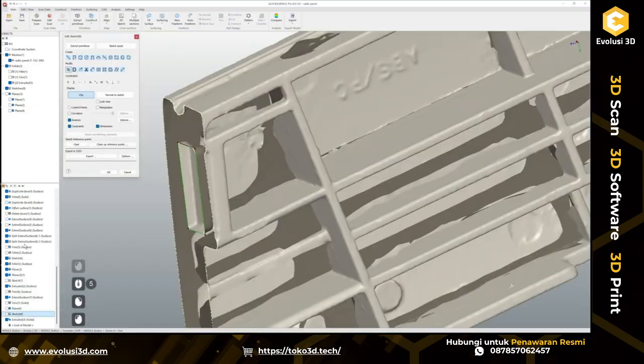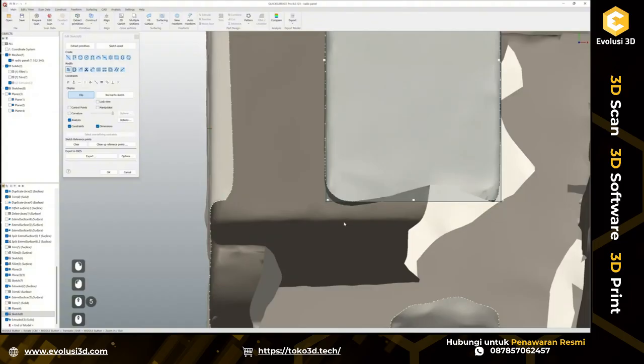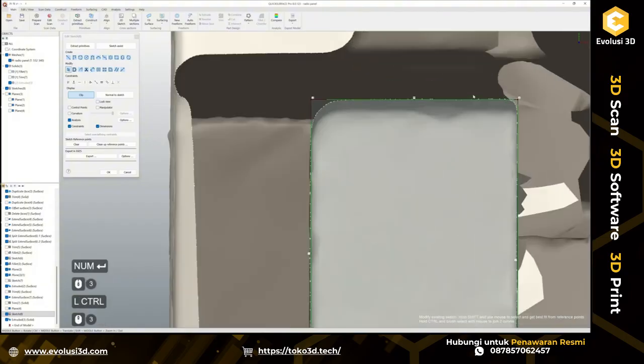Probably I could go back to the sketch to add fillets actually here. So it's 0.93. Well, maybe 1 millimeter is a bit too much. Say 0.9. On this side, 0.5 probably.